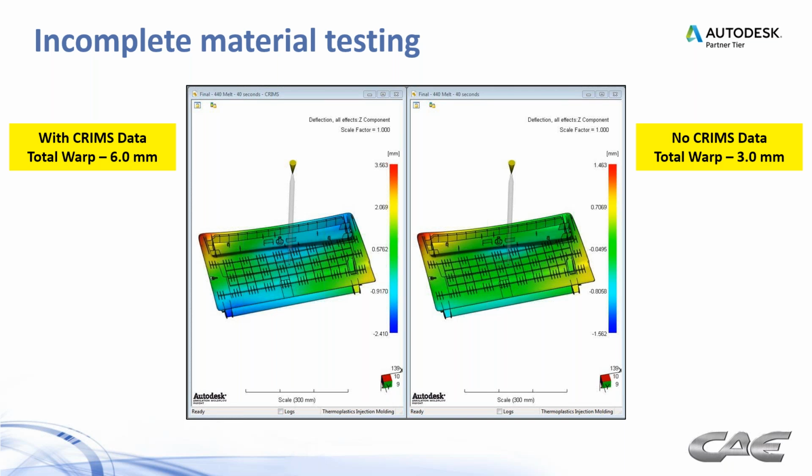And after they started molding parts, they noticed that the warpage was actually much higher than that. So by that time, GM had started their materials database, and that material became available, and we reran it, and it actually predicts 6 millimeters, which was more in line with what they were seeing at the press. So the cavity half of the mold was scrapped, new manifold built. We ended up having three gate locations, and we were able to flatten that part out. But at the cost of time and money. So it's really important to have good material data across the board for any analysis, and everybody should be insisting on that.